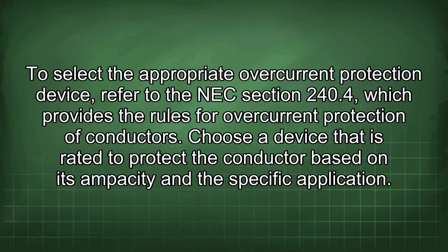To select the appropriate overcurrent protection device, refer to NEC section 240.4, which provides the rules for overcurrent protection of conductors. Choose a device that is rated to protect the conductor based on its ampacity and the specific application.